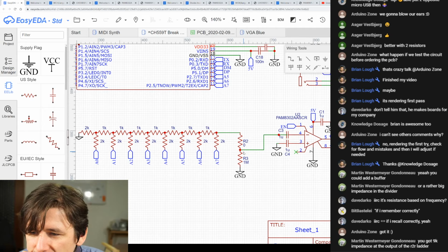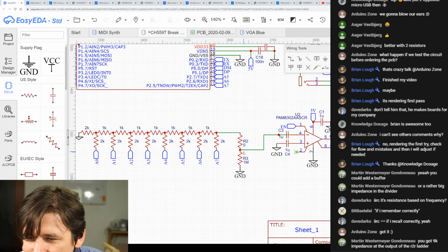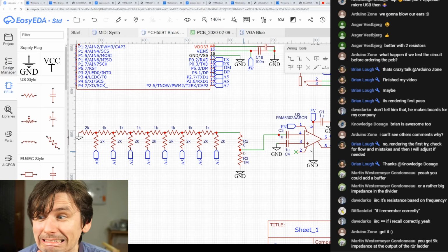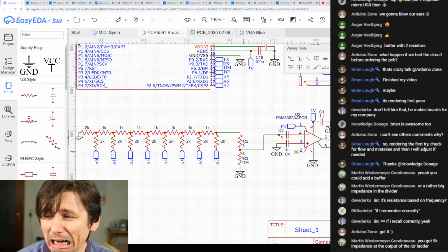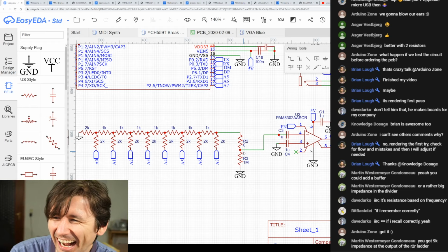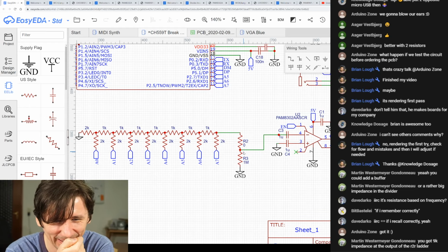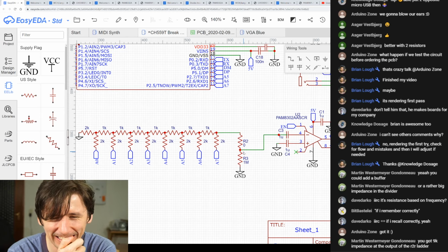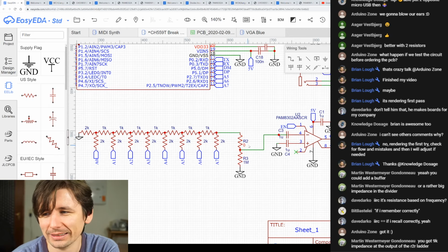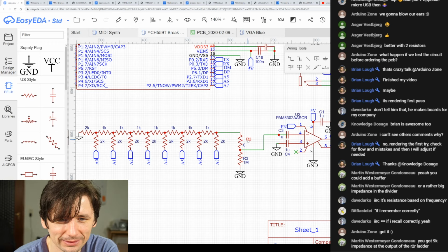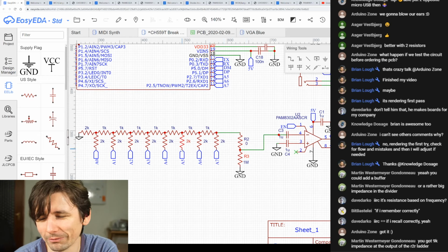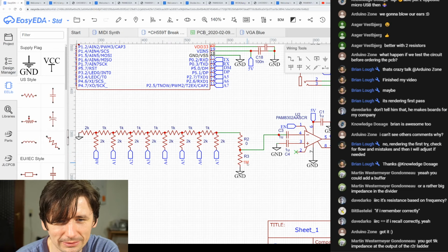You got 9K impedance at the output of the R to R ladder. Okay. And now, I'm a software engineer. Help! Oh, I see that failing here. Okay, for now I have only this 0 ohm resistor here, and one mega ohm for here. So now it will simply do nothing. Maybe even not populating this.